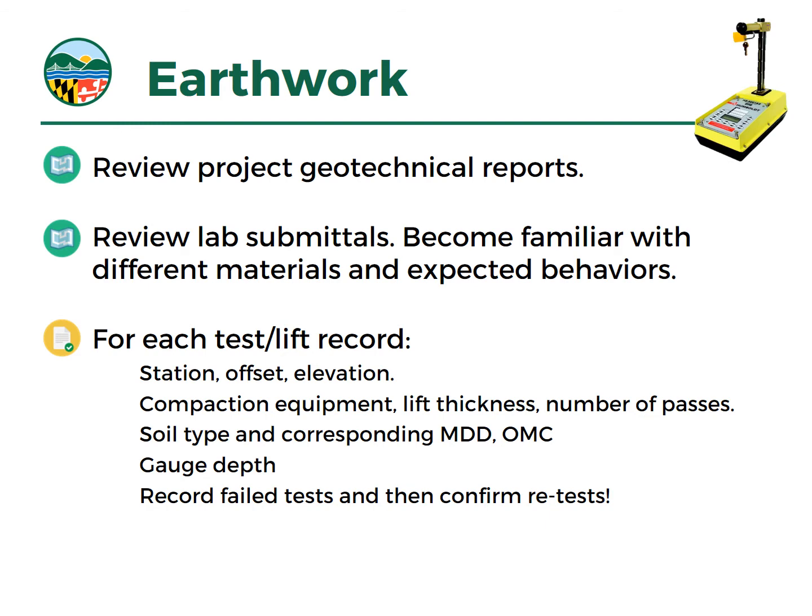But they need to have that material accessible ahead of time so they can prepare for their field work. And of course, for each test and each lift, record the location of the testing, the type of compaction equipment used, the lift thickness, and number of passes. Record what soil type you're testing for, and then the results of that test. And like I said before, the failed tests and the retests should all be recorded.